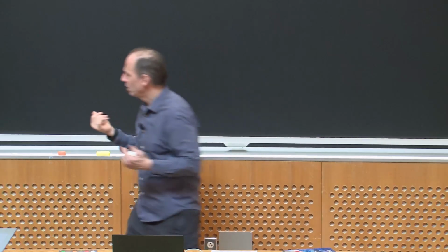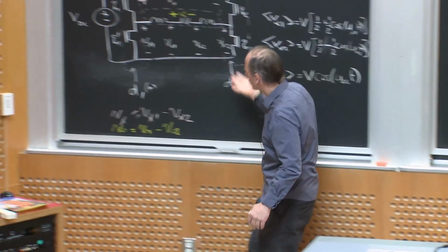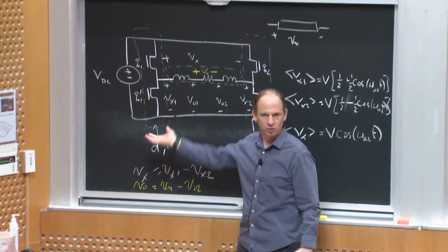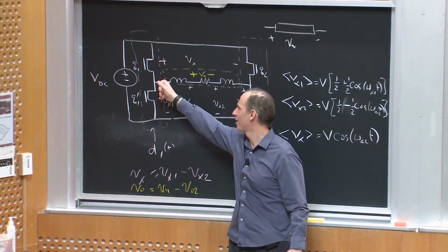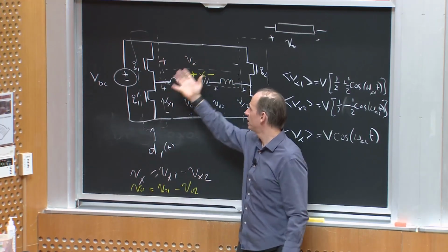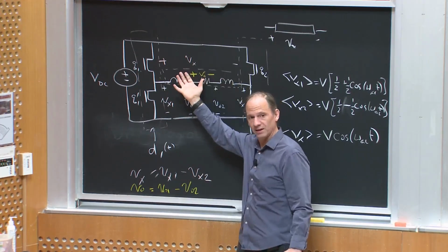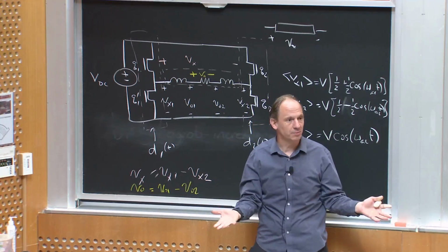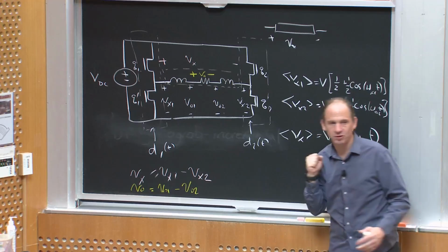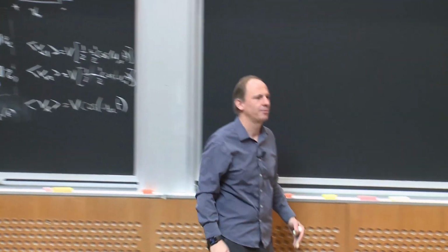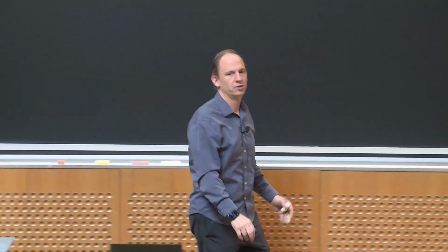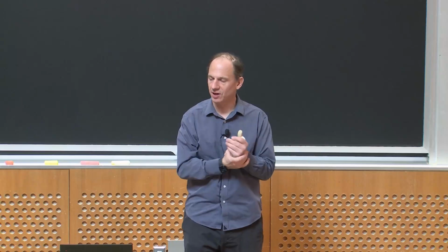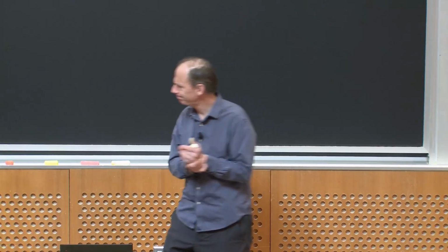Now, the average voltage that we get is just due to PWM, right? So I can control this average voltage and this average voltage. The details of how much ripple I get and what its high frequency AC components are depend upon how we do the PWM. And we talked last time about different ways we could do that, but it's the same exact concept, all right?